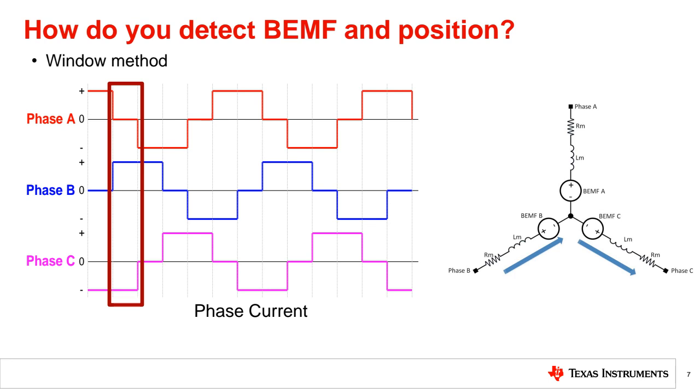It means 100 volt. If you read, for example, 1 volt, 3.3 is equal to 100. 1 volt, what? 1 times 100 over 3.3. Probably it means that now I am reading nearly 30 volt. This is the ADC working principle.